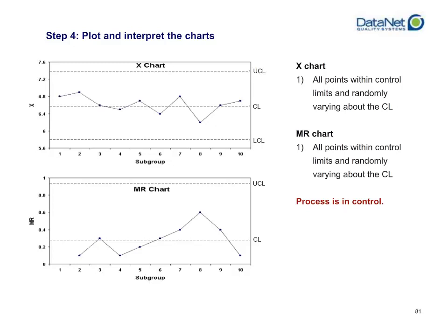If you had begun tampering around and started trying to change your process for your pencil diameter around subgroup number 8, you might have shifted it adversely where you would push your process too far down, and you may have gotten some out of control points because naturally when this process was moving forward between subgroup number 4 and subgroup number 8, that was just some natural variation where it happened to be going up in 5 consecutive points